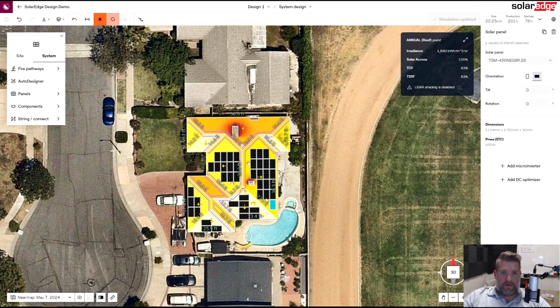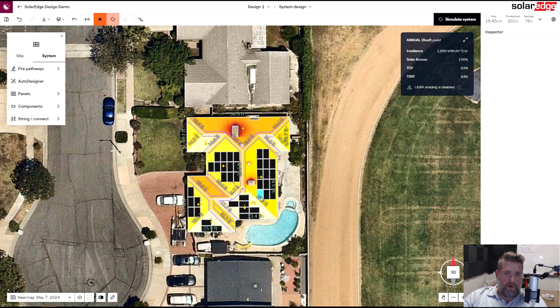What I typically like to do is have a conversation and say, okay, which panels are meaningful to the homeowner? Do they want to keep what is meaningful to my installers and easy to install? Some homeowners don't like solar panels on the front of their roof. Now, in this case, this is the west face, and these solar panels would be the best opportunity for high price offset and production in the on peak time, which is what we want. So I'm actually more likely to move these east facing modules so we can take advantage of our power hours.